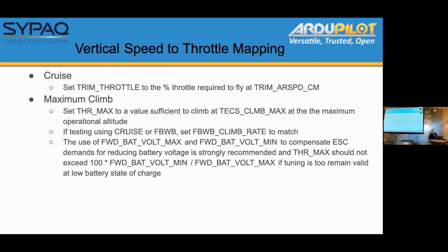If you have a cylindrical cell from manufacturer B, they may specify it's safe to take that cell down to 2.8 volts. And that's a much bigger voltage range ratiometrically than the pouch cell. That's why in multi-rotors, for our thrust linearization, we do have a battery max, and then the battery can obviously go below, but that's a safe range of gains.